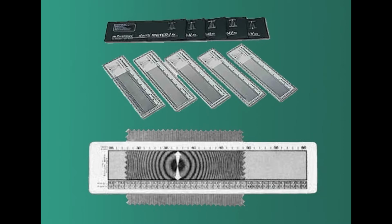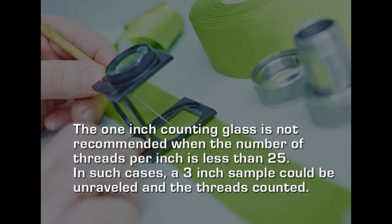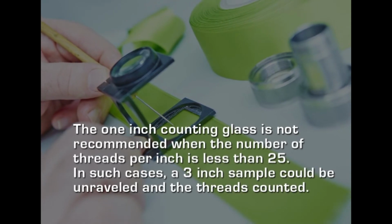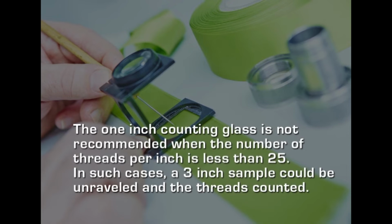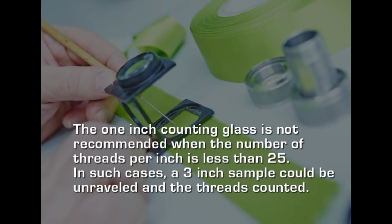The regions near the selvage edges should be avoided because the spacing of the threads is often a little different than in the body of the cloth. The 1 inch counting glass is not recommended when the number of threads per inch is less than 25. In such cases, a 3 inch sample could be unravelled and the threads counted, and the result can be converted to 1 inch.